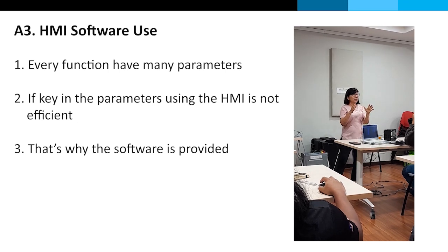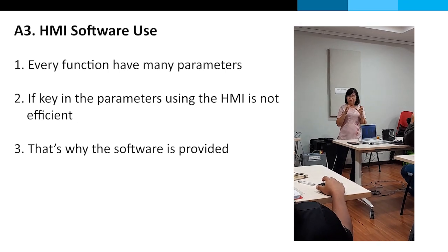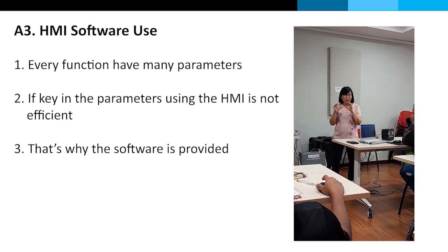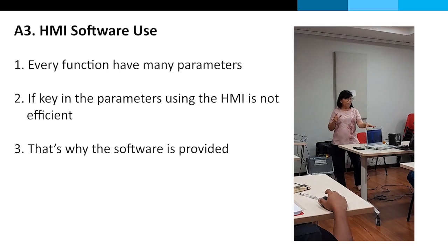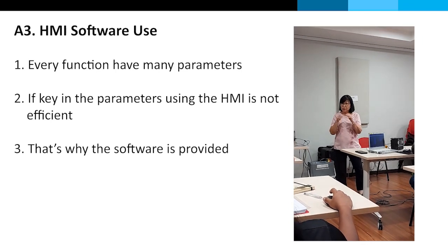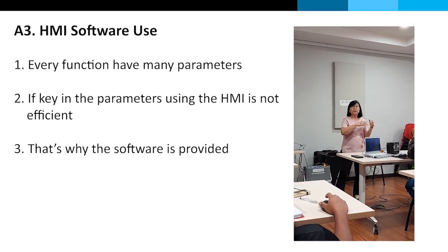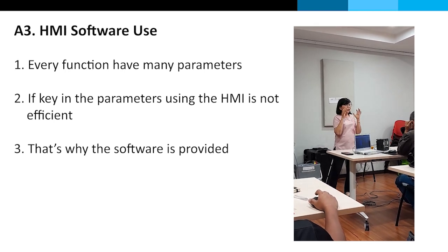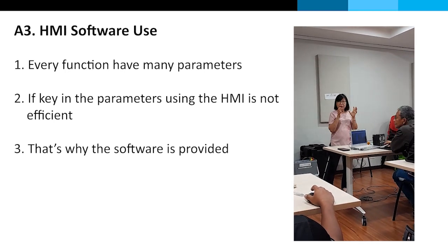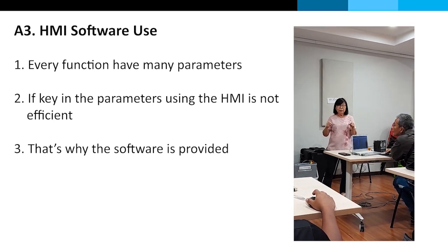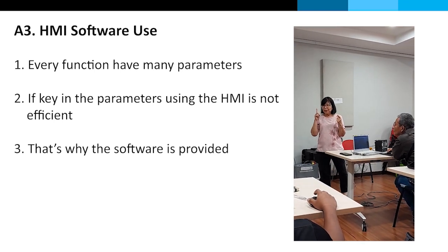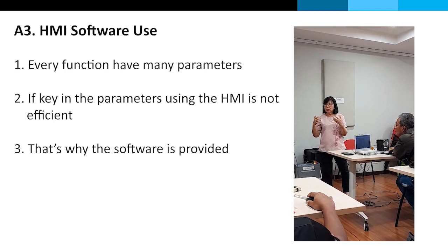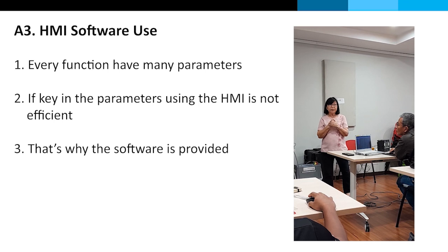That is why the relay manufacturers give you a software whereby you can key in all your settings on your computer, even though your relay is not powered up. So you can key in the settings, you can print out the settings to do one final check, and then if you are confident that you've got the right settings, you can upload to the relay one time. Okay, so it helps you to do setting very quickly.